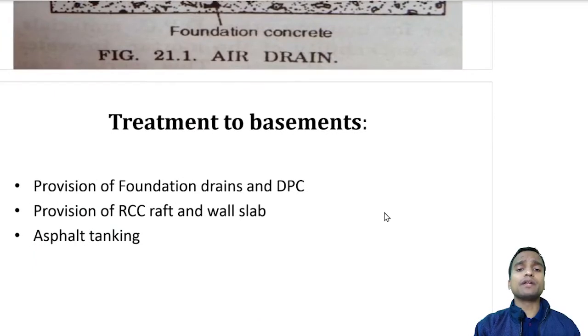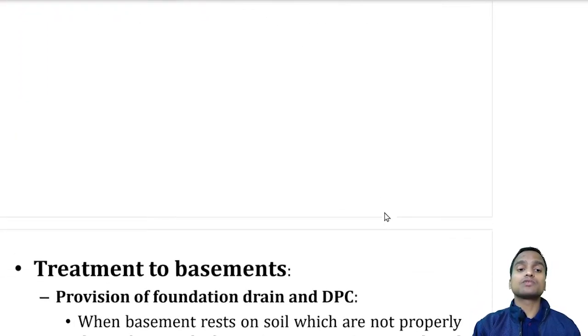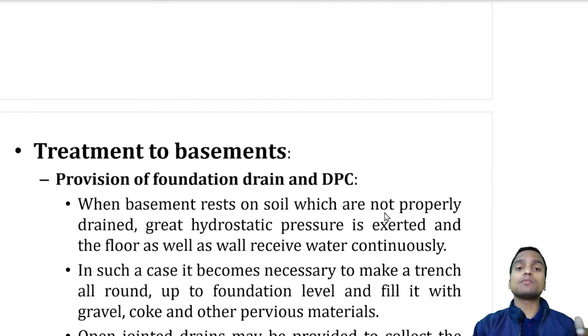Now how do we treat the basements for preventing the dampness? So it can be done either by provision of foundation drains or DPC, or by provision of RCC raft and wall slab, or by the provision of asphalt tanking. Okay, so these are different treatments to basements.